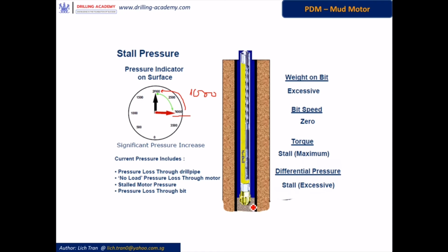Alright, when you have mud motor stalls often, frequently, you may destroy the motor, you may cause damage to the stator and rotor, the stator rubber, and you may shorten the service life of the motor. You may not achieve the whole section within one motor run.